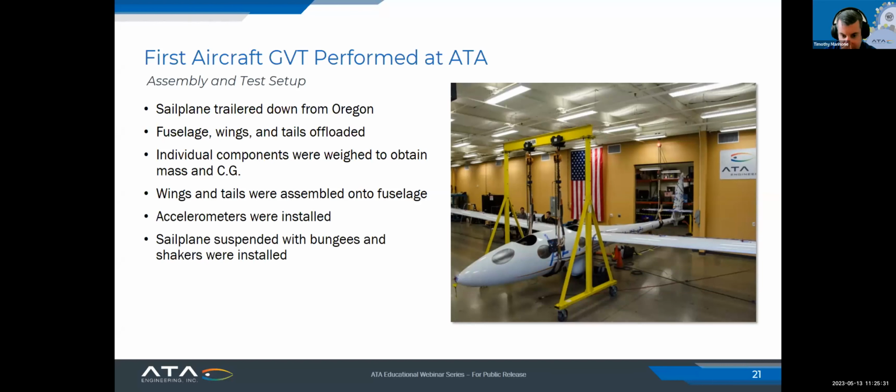Yeah, that was a big study: what sort of mass they needed on the control surfaces in order to make them more dynamically stable, to shift frequencies around. So there was a fair bit of trade studies involved with that. The nice thing was that those masses were on the order of a couple pounds, so they didn't have to be huge. They just had to be located at the right locations.